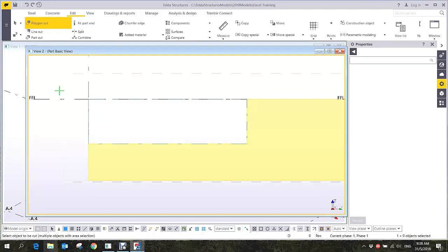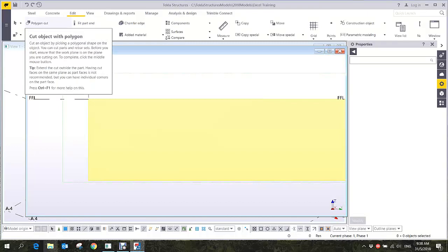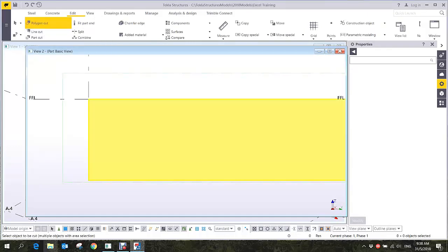Again, I'll do it again. You can also delete the cut. So here, polygon cut. Pick the part to be cut. Okay, and then 1. So here, let's say 1750, 600, 1750. Middle button of your mouse. So that numeric value that shows up helps us a lot. Is the increment only by 50, or can we set it by every 10? No, actually even 1.